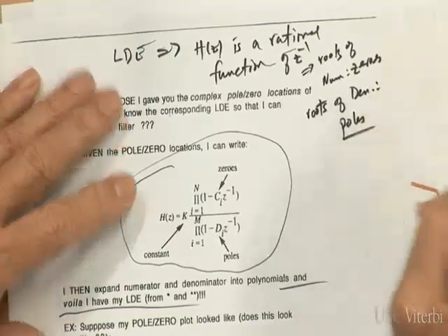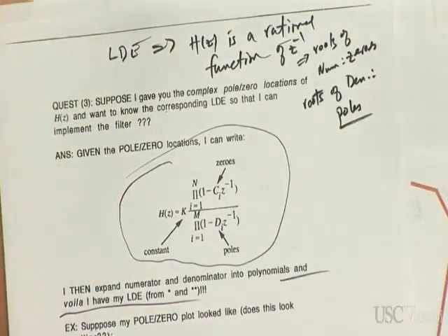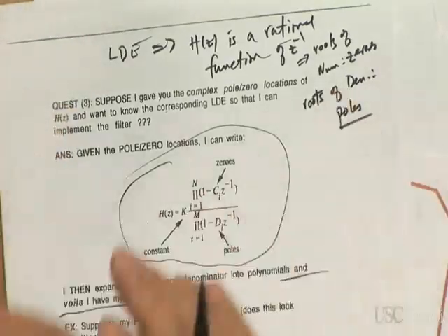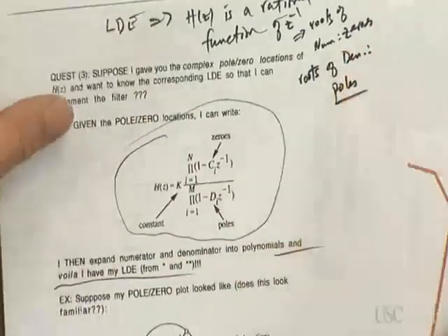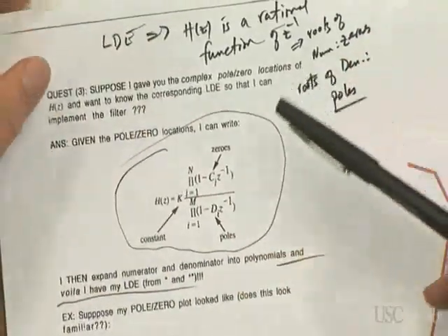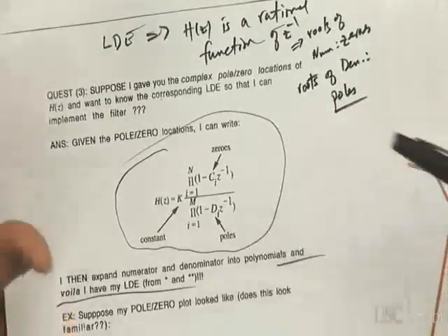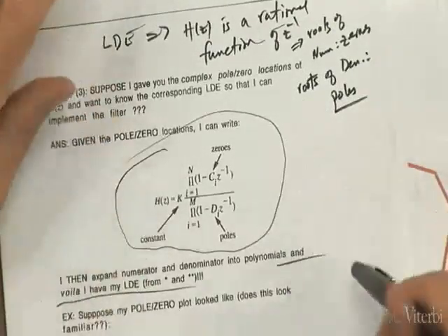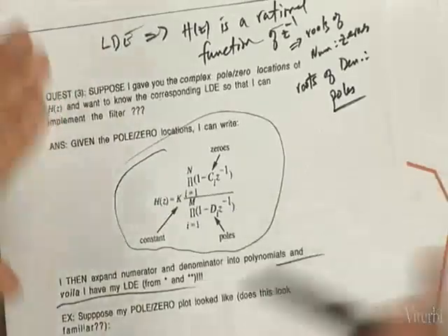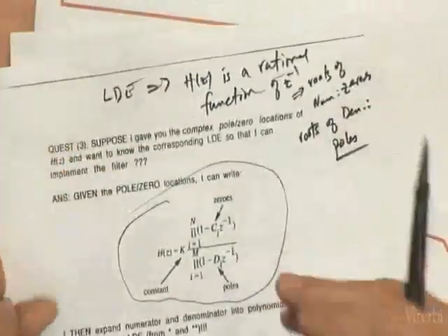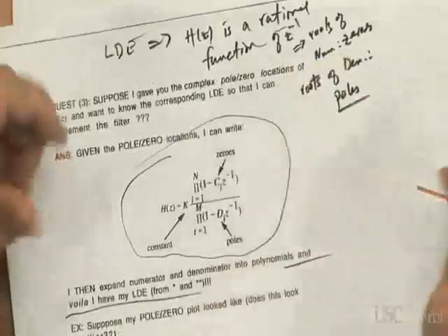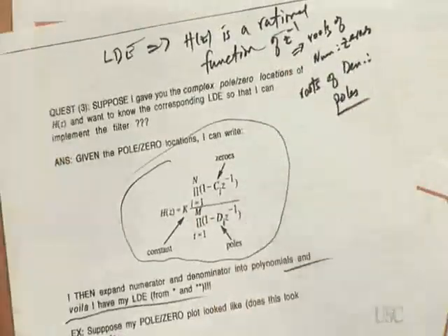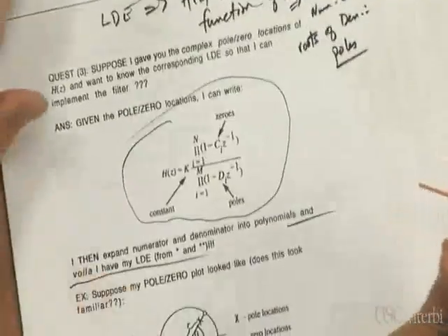then normally you're given a quadratic or a cubic or a quartic polynomial, and the question is what are the roots of that? That's a difficult problem without packages like MATLAB. But the other way is not quite as bad. If I tell you what the poles and zeros are, then you can just write the numerator and denominator in factored form.